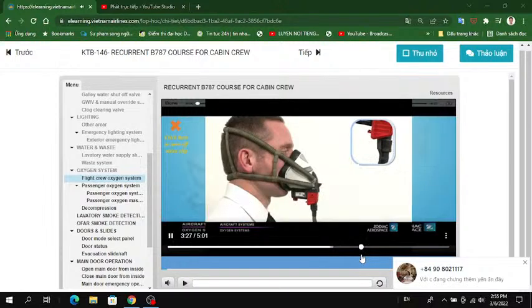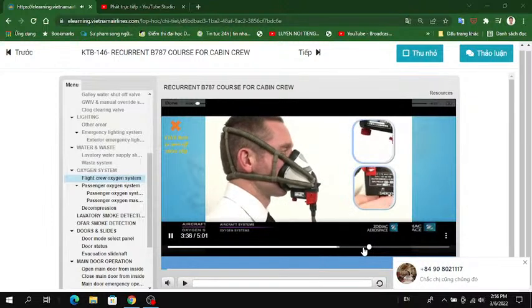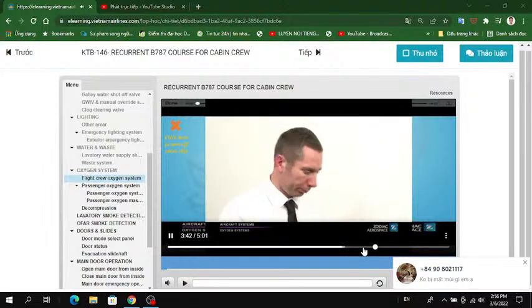Stowage. Make sure that the dilution rocker is pushed upwards in 100% mode. Make sure also to deactivate the emergency mode by rotating the press to test and emergency knob clockwise. Remove the mask by pressing and holding the red tabs. Open the stowage box doors.